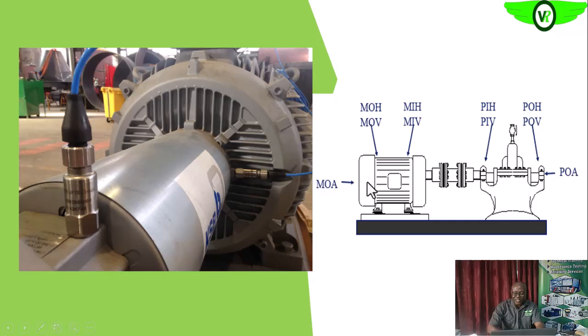So these are the three orientations: the outboard axial, outboard horizontal, outboard vertical, that you take the vibration information on, on the electric motor outboard end, that is the non-drive end. Then on the drive end, you take the inboard vertical, which is the same orientation like this, because you place it on top. Then the inboard horizontal, you place it on the horizontal axis, that is the x axis to the bearing.